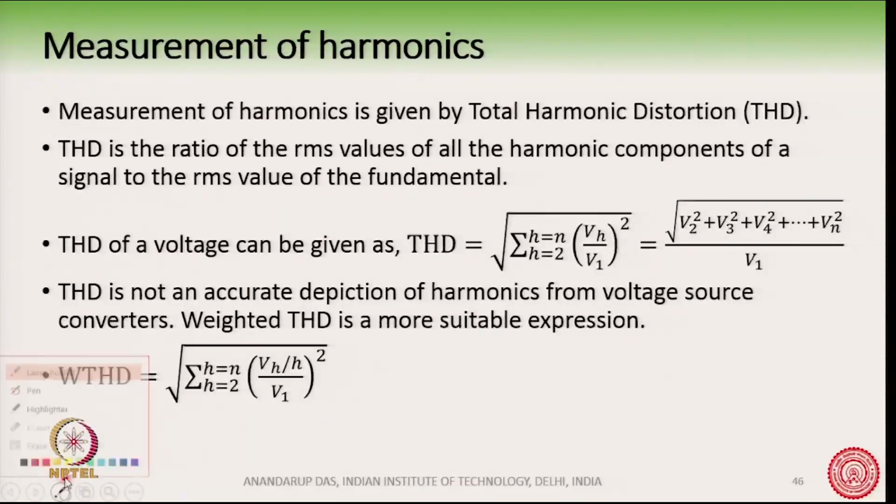So, for example, suppose I have a voltage source converter and I have PWM techniques. In one PWM technique, the output voltage has the fundamental, and these are some harmonics which I have produced, around 5th, 7th, and this is the fundamental.